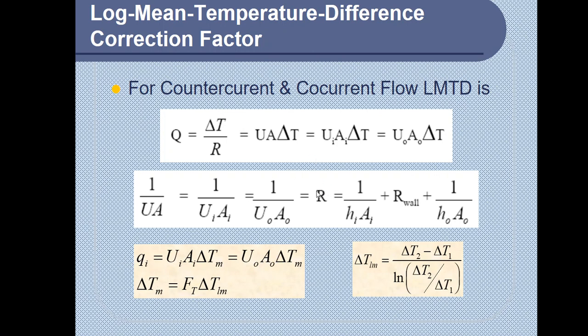Now, what about the formula that you are seeing here on top? In the case of heat transfer to and from the heating medium and to the medium to be heated, that would be this particular general equation. The rate of heat transfer is equal to the temperature driving force divided by the summation of all resistances to heat flow.